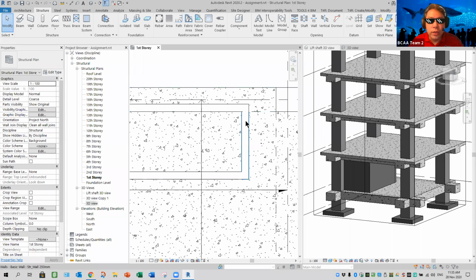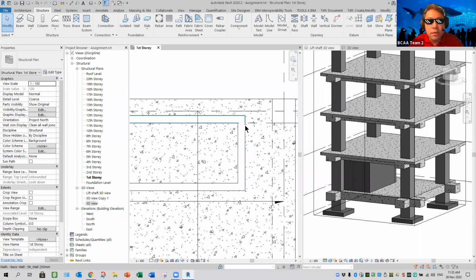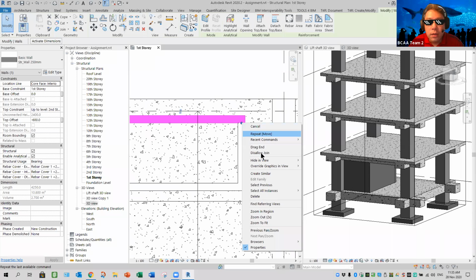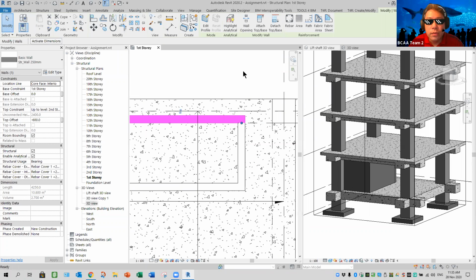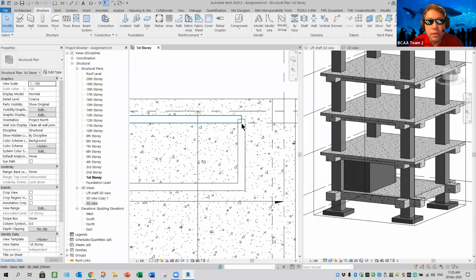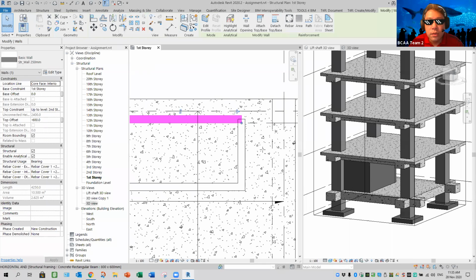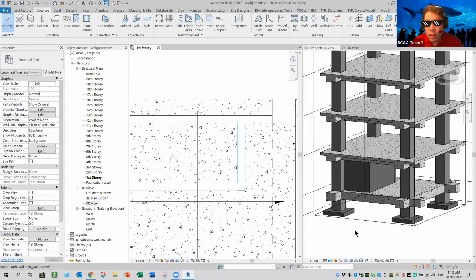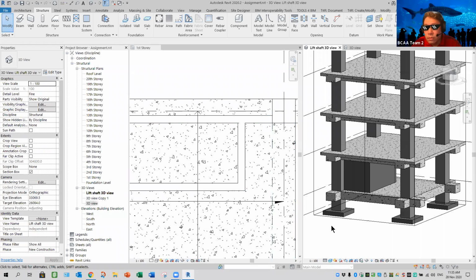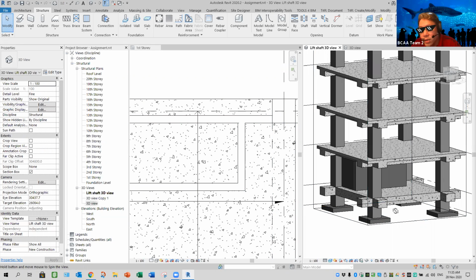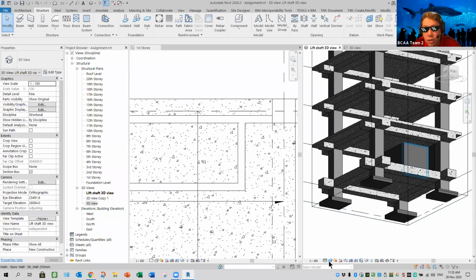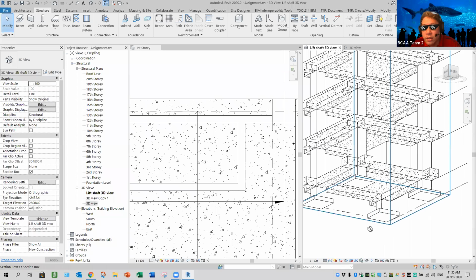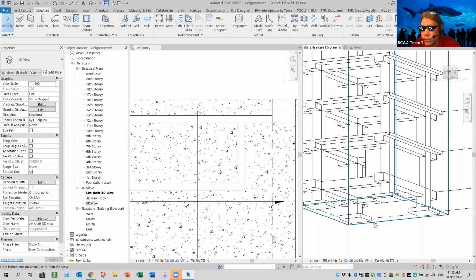Because this is a connected joint, so I don't want this. So right click, disallow join. So I'm going to drag this to here. Yep. Okay, hopefully the model is still done up nicely. I should see all my line work nicely. So I need to create 2 more beams.